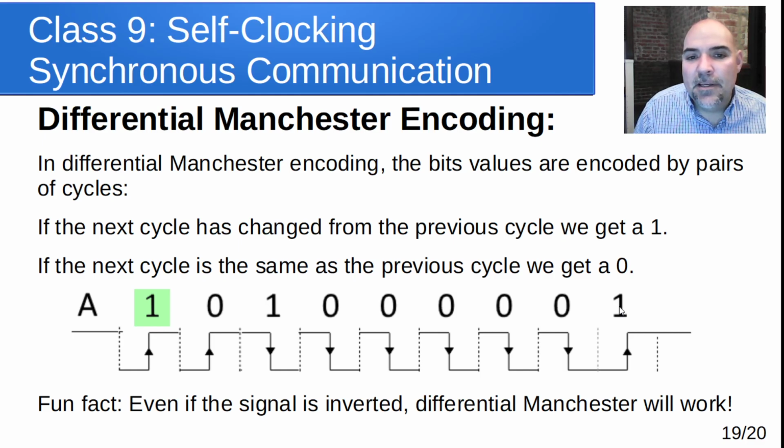And Manchester encoding is really simple to implement but very robust. One of the advantages of it is that those edges always wind up in the middle of those pulses. So if you were to time off every pulse, we see an edge. That can be an advantage because it makes the frequency band at which that communication runs very consistent no matter what data you're sending.